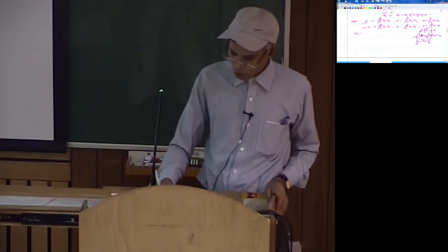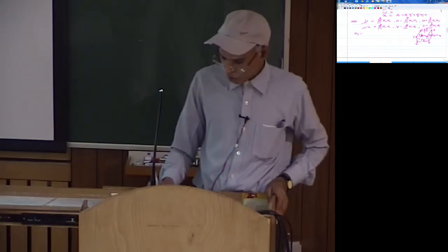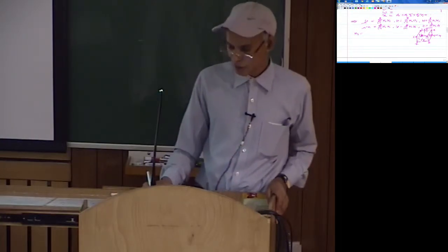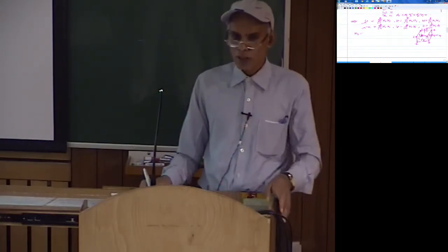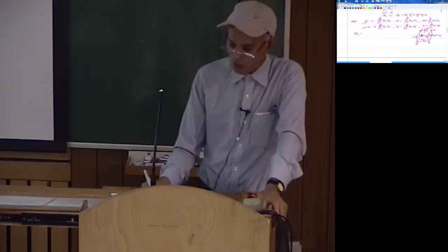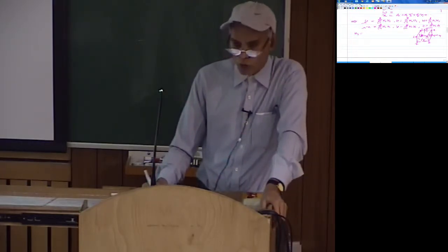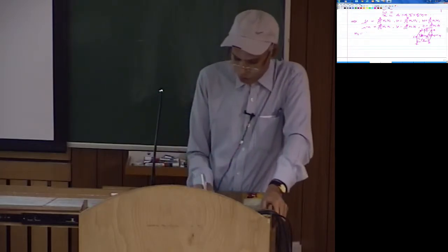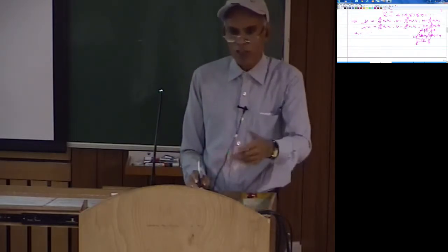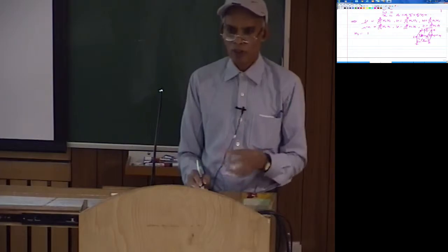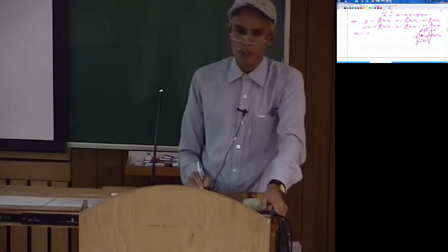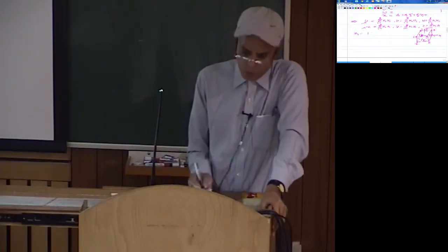So what would be the equation of this face, which is 6, 2, 3 and 7? Xi equal to 1, because this is the face where xi is 1. So you can write that as 1 minus xi, because xi is varying from minus 1 to plus 1. Rather than writing xi minus 1, we write 1 minus xi so that it will always be positive.